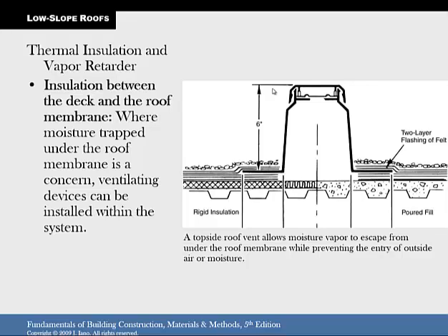So, you also need to, when you have penetrations in your roof, take care to detail that correctly. And this is a detail for that. Again, these are things you could copy for extra credit if you need it. This is showing the metal roof decking, like we saw in that picture earlier, with a lightweight concrete. Then you got some tar layers, and there's flashing going over that. Then there's another layer of roofing, so it'll be very hard for water to get all the way down into there.